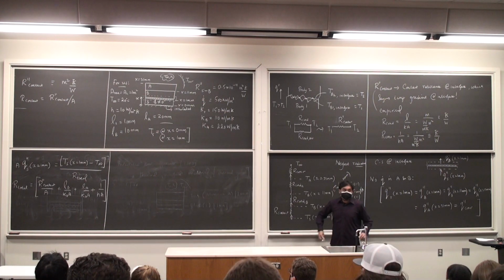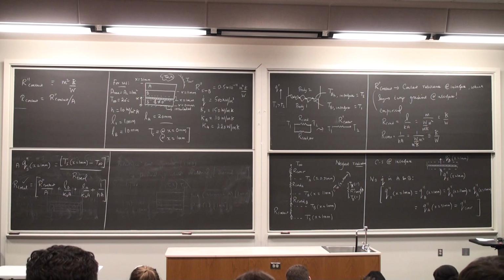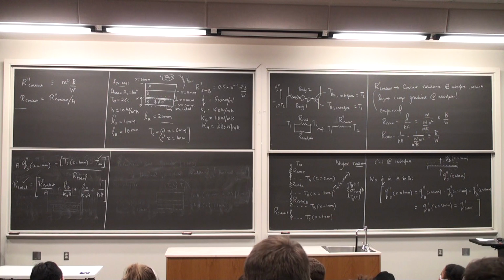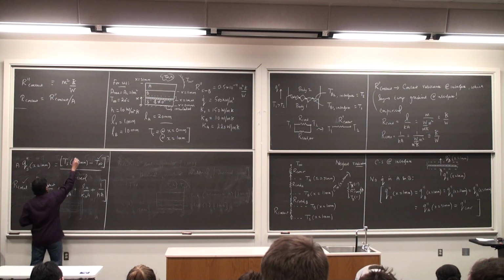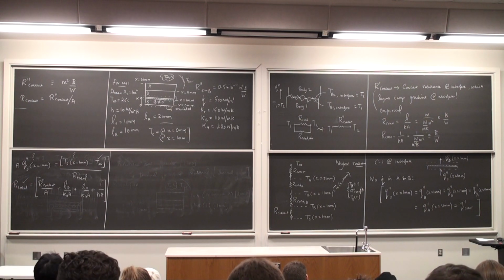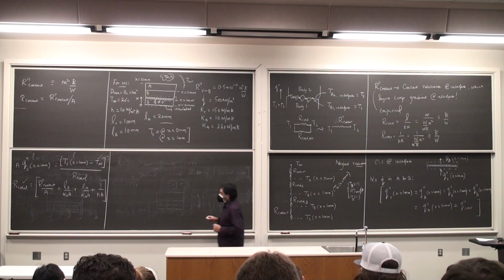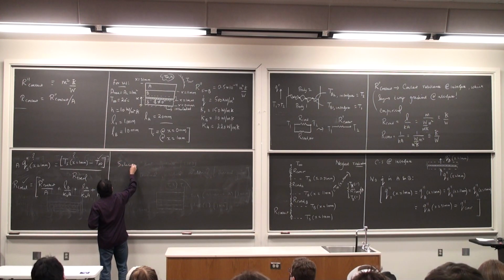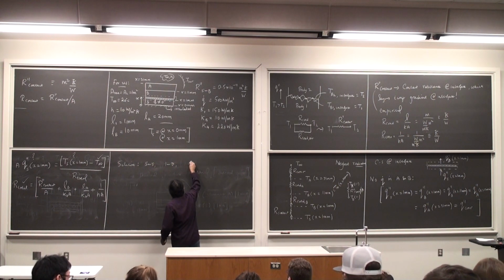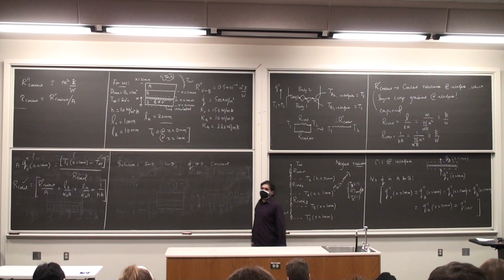Alright, so things that I know: R total, because I know everything regarding the problem parameters. I know T infinity. Obviously I don't know Ts at x is equal to 1 millimeter, and I don't know this guy as well. Which means that I go back to the silicon chip because there is heat generation, and I use the heat diffusion equation. So look at the HDE. Steady state, 1D, Q dot is not 0 and is constant. It's given to us: 500 kilowatts per meter cube.